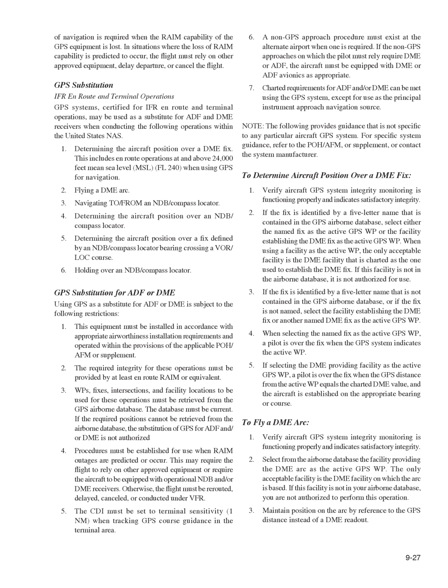GPS substitution, IFR en route and terminal operations. GPS systems, certified for IFR en route and terminal operations, may be used as a substitute for ADF and DME receivers when conducting the following operations within the United States NAS.